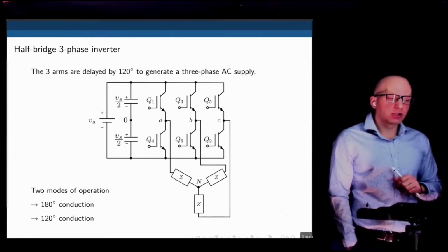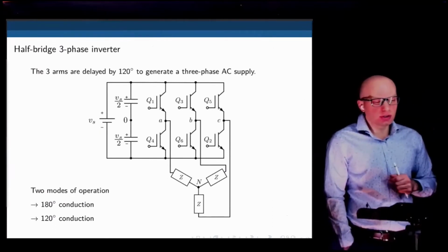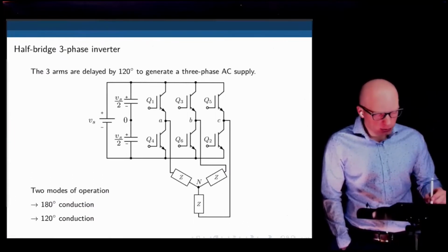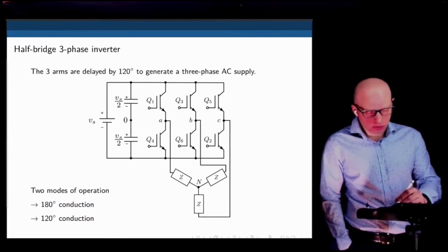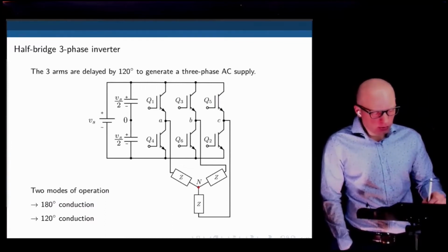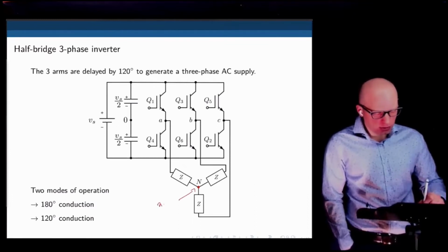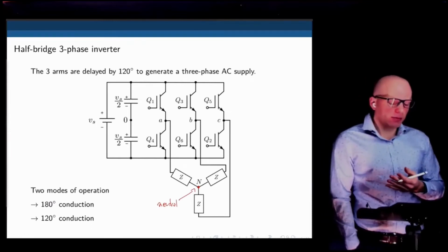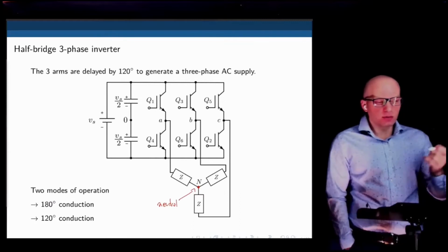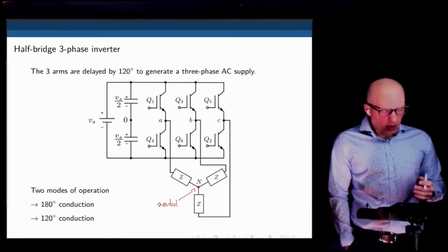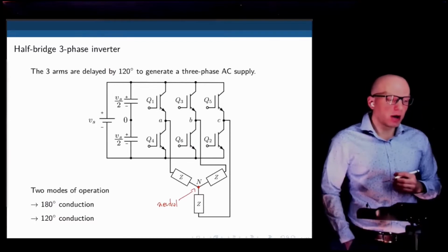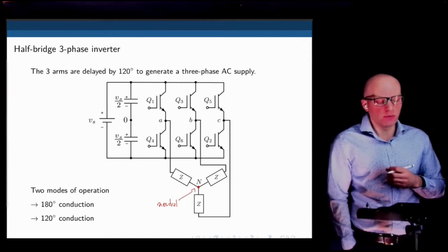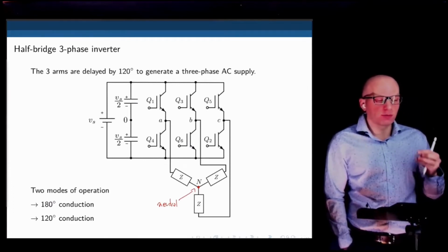Here it is. We actually would only need 6 transistors to do that. And the difference compared to what we saw before is that we now create a common point for all these transistors to deliver power to with a balanced load. And this point here is the neutral point. So now we see one bridge inverter as the same we had before with this extra leg, Q6, Q2 on the right. And each bridge now powers a load Z. You see that the load is balanced. That's one of the assumptions that we are going to make moving forward. The load in a 3-phase inverter is always balanced.